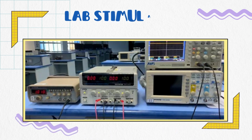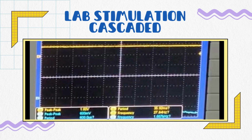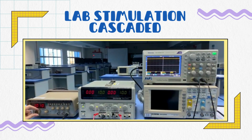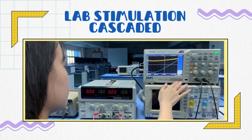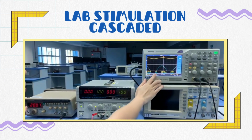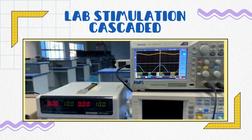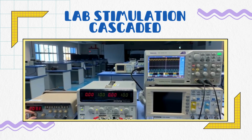I'm going to explain the working principle of this circuit. So at 1 Hz, the output voltage is less than the input voltage. This means that the gain is less than 1. So I'm going to change the frequency to 20 Hz, and the output voltage is way higher than the input voltage, which is 32 volts. So the gain of this circuit at 20 Hz is 10.